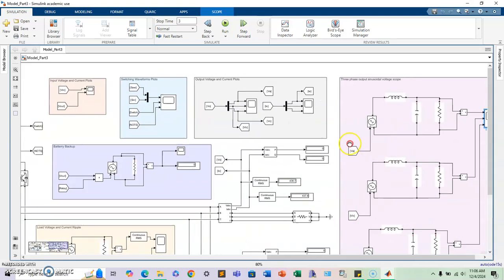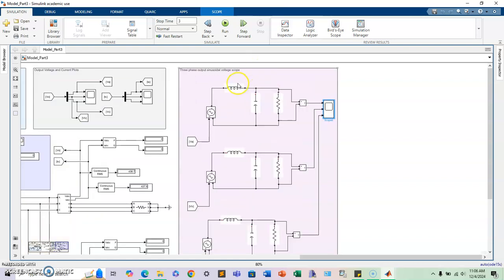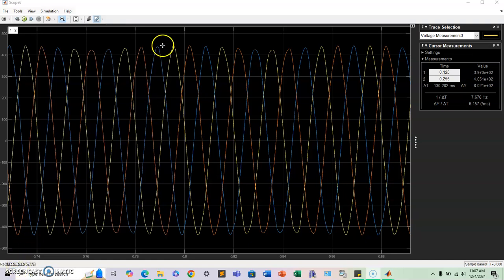Okay, so finally, this is for the sinusoidal. Notice how I have a low pass filter for the sinusoidal, because before I had just the hard switch, and I'll show you the scope once I have it. This is the three-phase sinusoidal on the filter. See how the sinusoidal has a little bit of an edge right here, but overall the three phases are actually pretty good themselves.